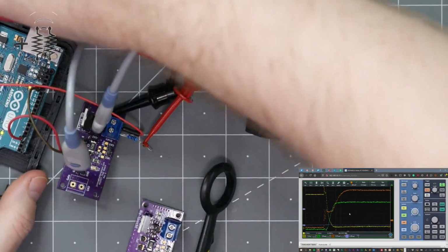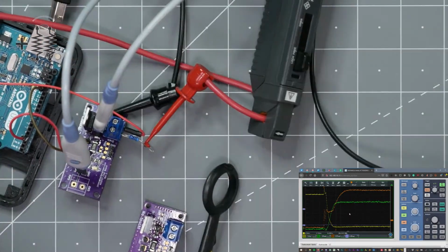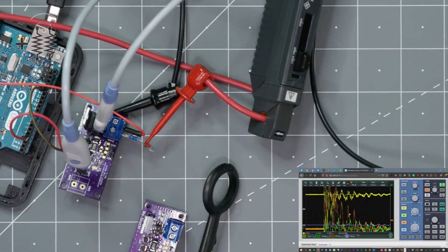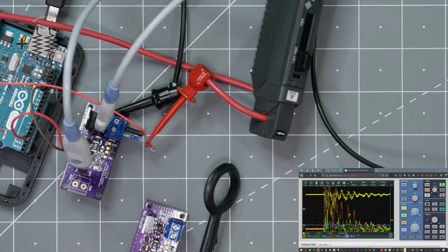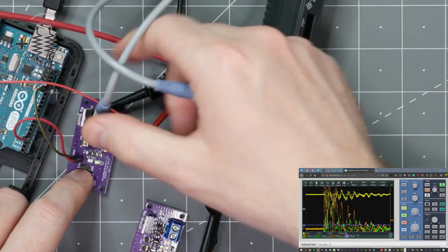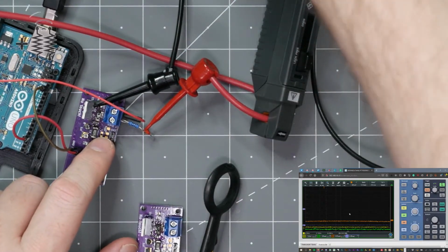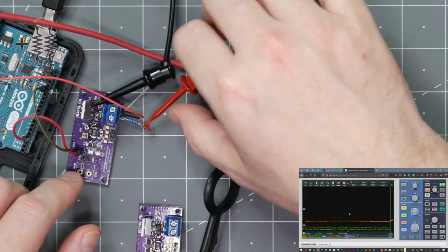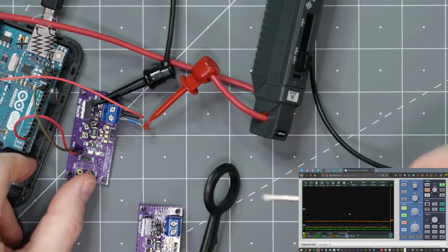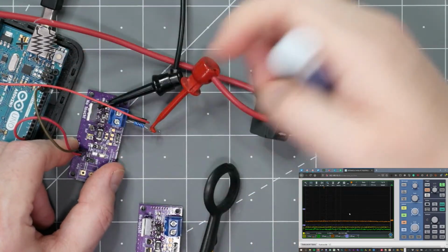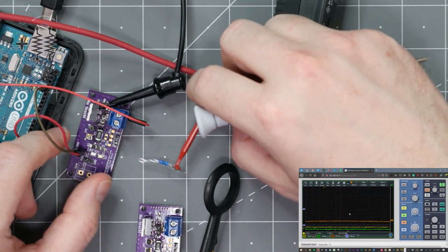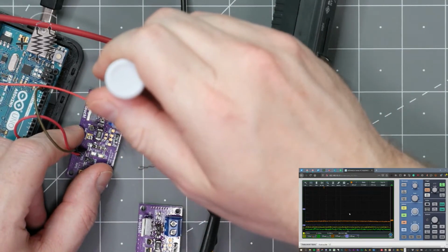So what I'm going to do is disconnect our Arduino, turn off the power supply just in case. Wow, that was some noise. Remove this probe and this probe, and then we will now remove our load resistor, which is 100 ohms. Which, by the way, is only rated for a 1/4 watt, but we're putting 1 watt through it.